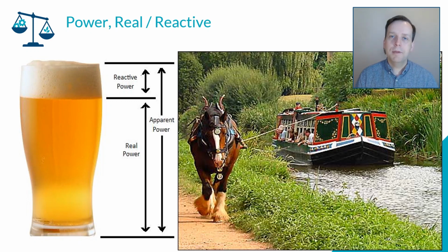Bit laboured, but it's just important to understand, particularly if you are in a factory with significant machinery, conveyor belts, blowers, compressors, that you probably have significant reactive power, and that is directly related to the total apparent power you are drawing from the electrical network.